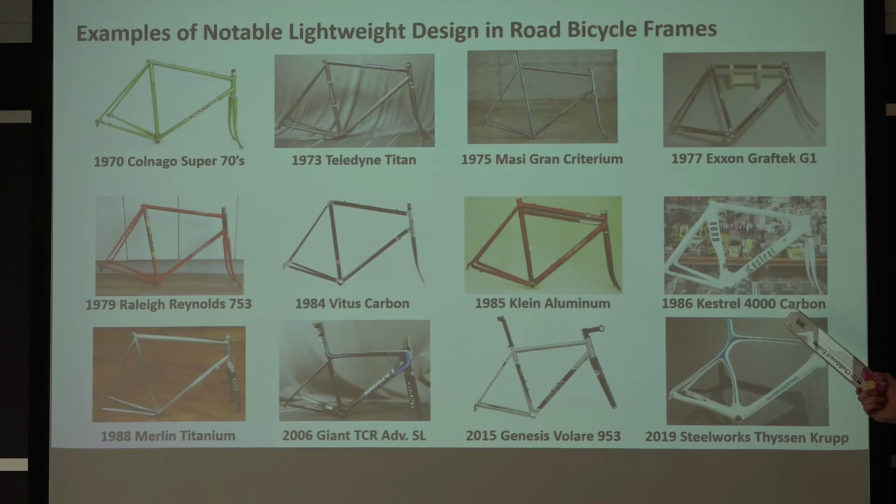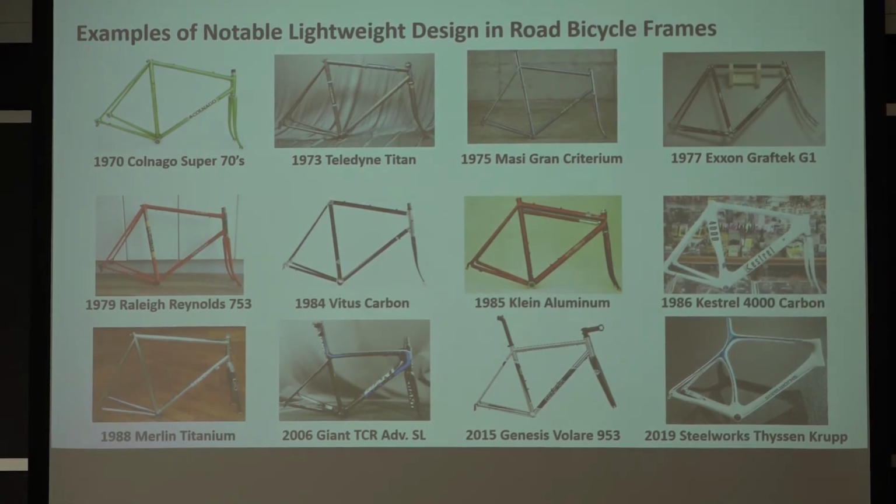This thing, as you can see, is pretty robust, and it probably wasn't that much lighter than a steel frame at the time. It was darn expensive, I remember. But you can see there's probably some overkill in material here, because I don't think they had the technology at that point to compact the carbon fiber to make sure there were no voids in the polymer matrix, and that the resin was all squeezed out as they laminated this carbon fiber.